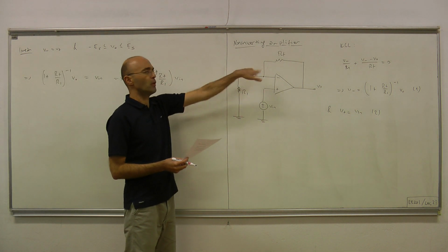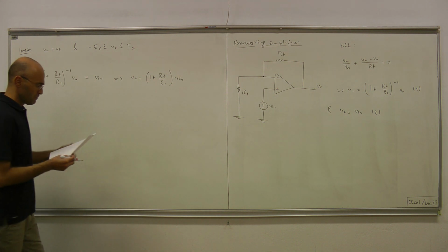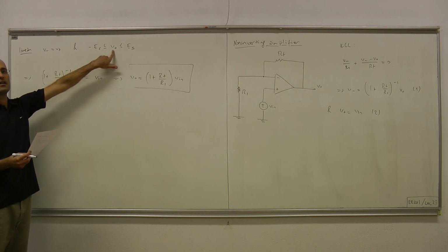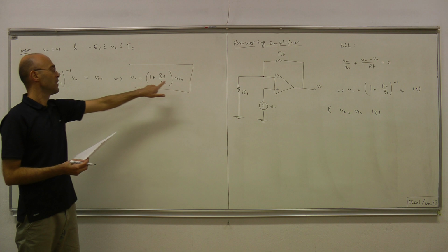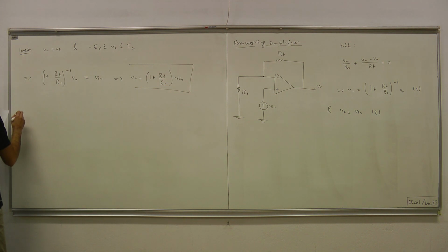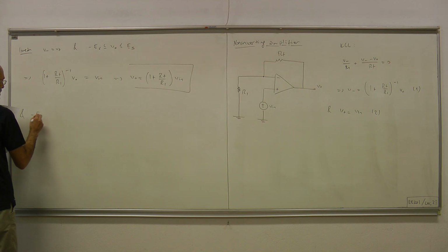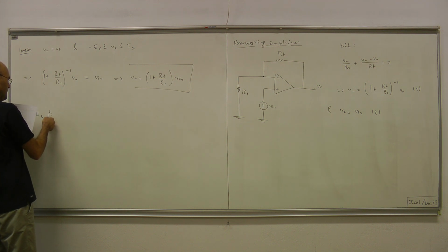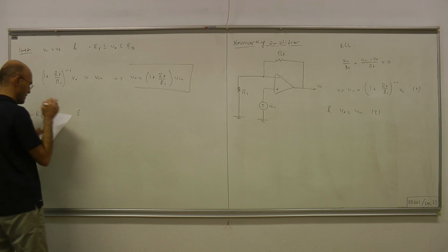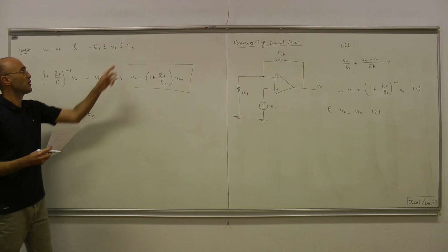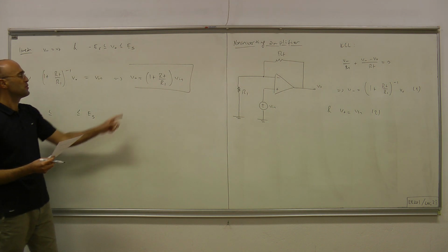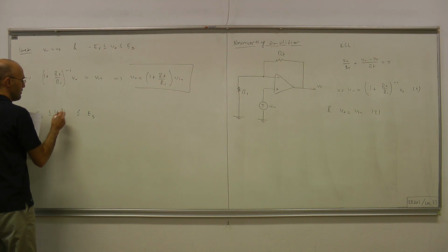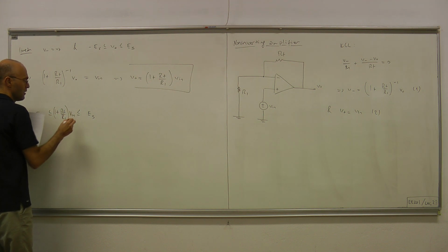Well, we're working with passive resistors. So this is the relation. We have to figure out one more thing, and that's the condition on the input voltage under which this relation holds. For that, we take minus ES less than or equal to V out, and that's less than or equal to ES. But instead of writing V out in the middle, we write V out in terms of V in: (1 plus RF over R1) V in.